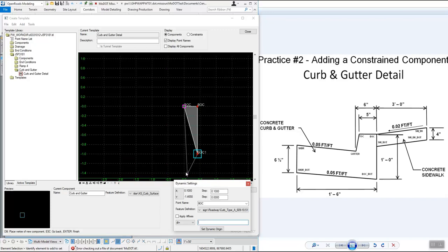The next one, we've got a 1 foot 6 inch bottom, but it goes up at 5%. So we'll do an HS, and we'll do the horizontal first, which is -1.5, or you could do a 1:6. We'll just do 1.5 and then comma.